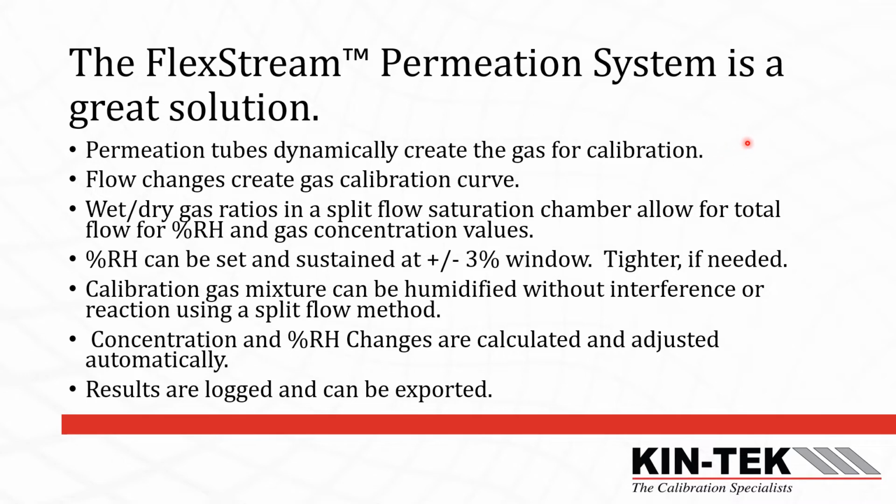KIN-TEK has a great solution to address all the challenges that I just discussed. It's the FlexStream permeation system. It uses permeation tubes in the base module that dynamically create the gas for calibration. So we create a dry gas there with the calibration gas mixture, whether it be BTEX, H2S, and so forth. And we can do the flow changes within the permeation system to create a gas calibration curve.